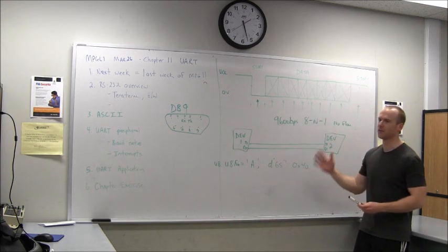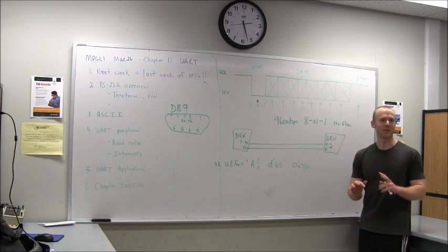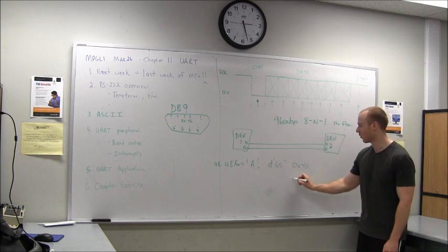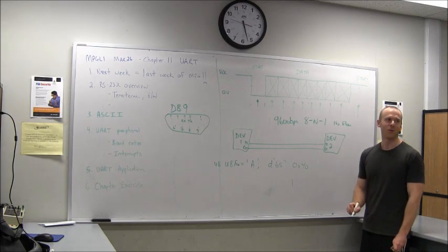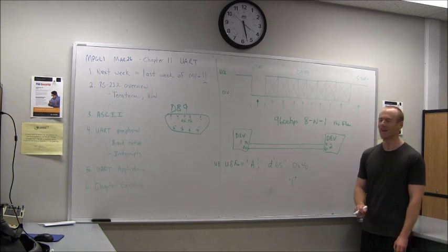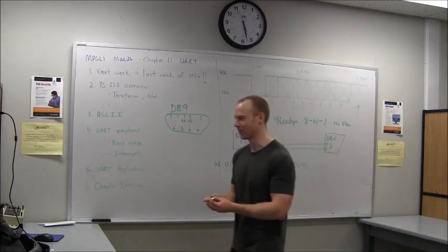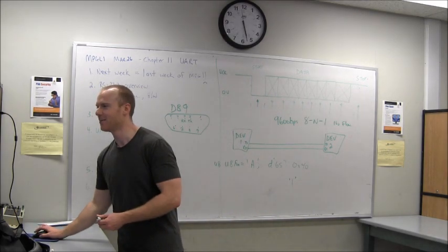When you're talking on serial port, especially when you're looking at a terminal program, when you type the number 1, you don't send 1. You're sending ASCII 1. Okay? Now, ASCII 1 is, let's bring up the table so I don't just guess at this.